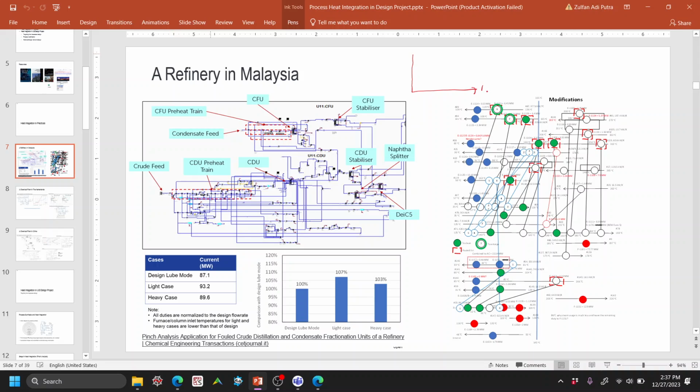So we plot in time, and then we have the Q, and then we have the data of flow rates, and then CP from either the data sheets of the heat exchangers or from our mass balance reconciliations. And then once we know the flow rate, CP, and temperature in and out, we can calculate the Q. And then from this Q, we can simply plot something like that, depending on the data that you have. But this is the typical heat exchange for each of the heat exchangers.